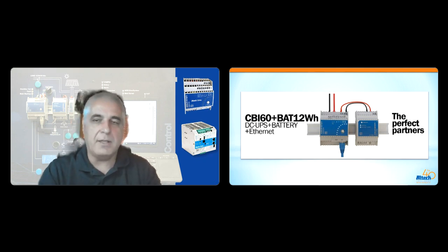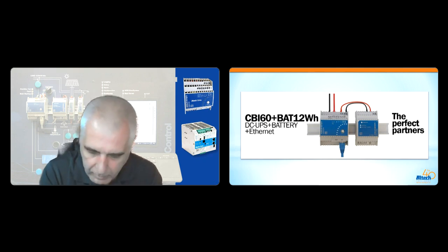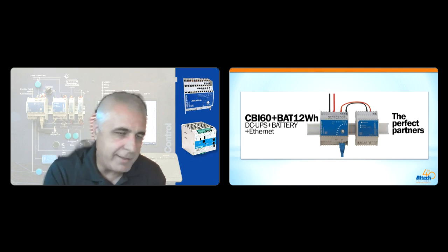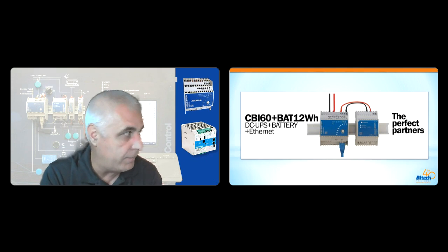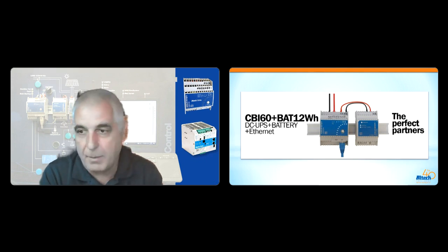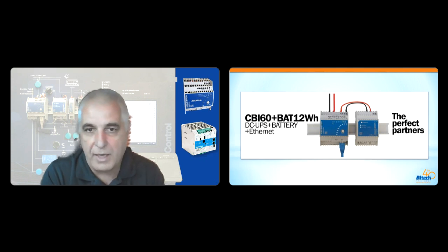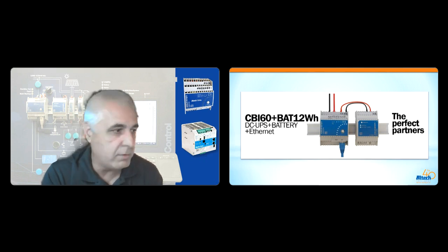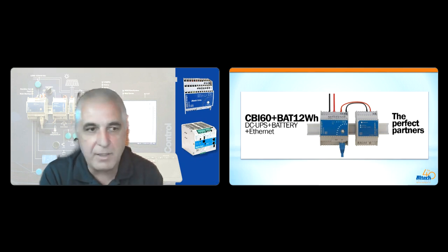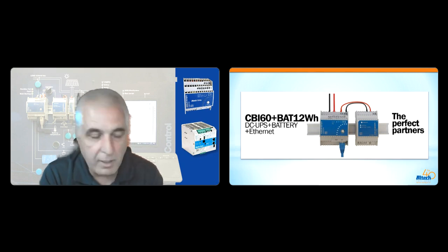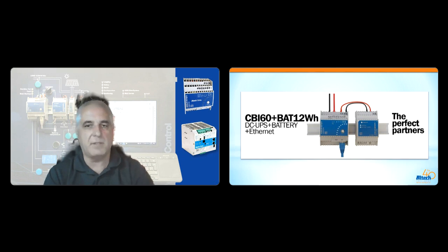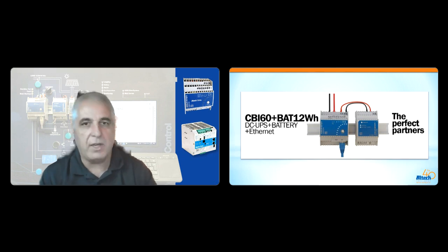So it turns out the computer that was mounted on the forklift was running on the forklift 12-volt system. And whenever they started the forklift, it created a surge, and then the computer restarted. It took them a while to realize there was a huge problem, because every time after lunch, there was a 20 minute restart of the computer system. And this plant used close to 100 forklifts, and at least 20 or 30 every day had this issue.